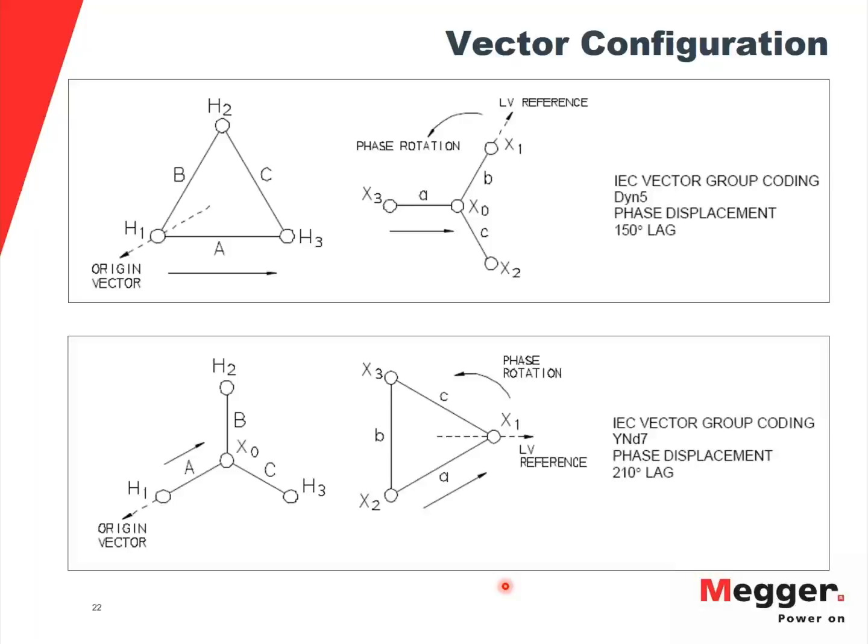The energy is still inside the inductor, and when you take the leads off, you might run into a possible arcing situation because that energy is going to dissipate through that broken connection. So from Megger standpoint, we do not recommend using a DLRO 100 for measuring winding resistance on large transformers.